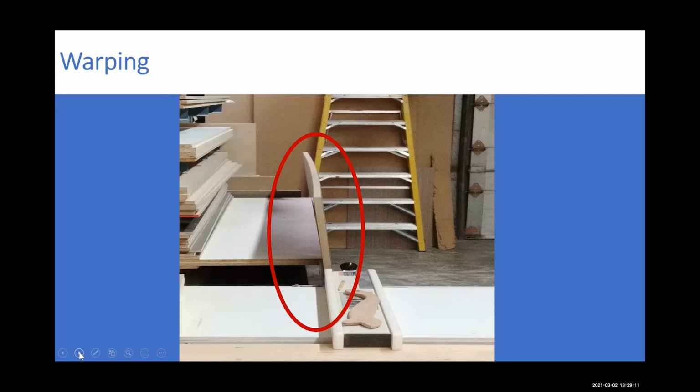So the laminate gets laid up on a moist piece of wood. As that dries out in the center, it causes something that was flat to warp. I've seen 3/4 inch MDF cup or warp up to 4 inches because of not acclimatizing the material.